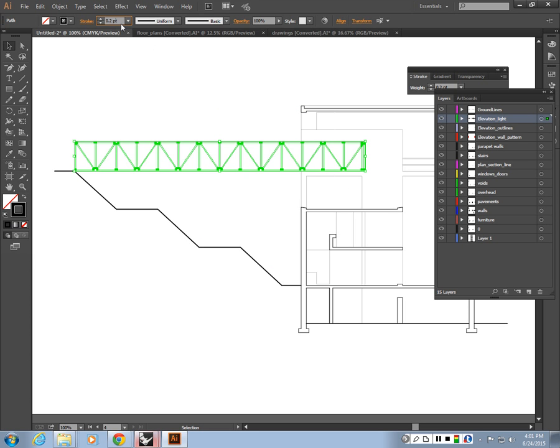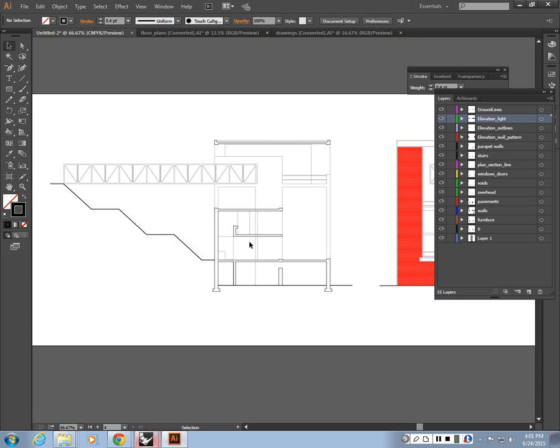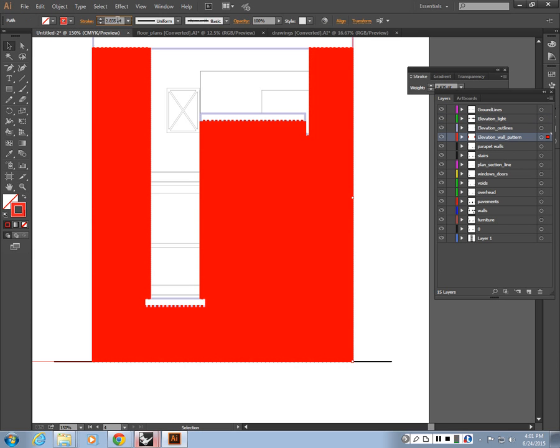So we assigned 0.2 to these elements in the back. This one is going to be darker, so let's make it 0.4. Right? So it comes to the front immediately because I'm establishing that graphic relationship between the elements. So these elements are cut. This is the closest element. The bridge is the closest element next in line, and then I'm further seeing the walls in the back. And if you have patterns on the facade, they should be the lightest, pretty much like how I did the pavement in the floor plan. So my elevation wall patterns should be 0.05. And everything should be grayscale, so everything should be black.